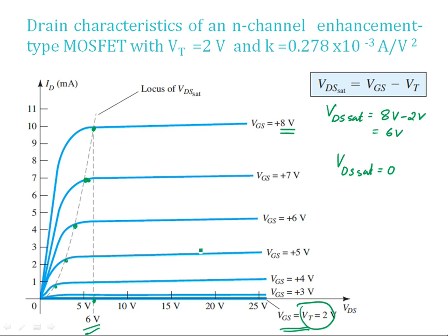Okay, so the enhanced current is 0 as VGS is equal to VT or below VT. That we know, we have discussed. There won't be any channel formation if VGS is less than the threshold voltage. Now as you move up again from VGS equal to VT, you make it greater than VT.